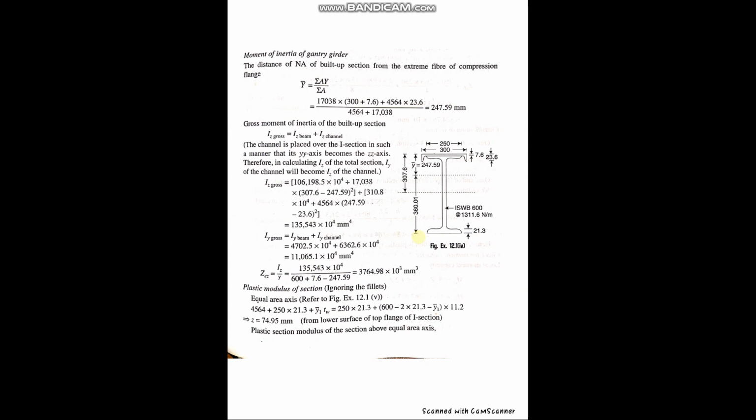If you take a higher value of section modulus, we are going to overestimate the section, and then obviously under that condition the bottom section will fail, but the top will remain as it is, right? So we don't want any portion of the section to fail. So to be on the safer side, we are going to take the smaller value of the section modulus. All right,